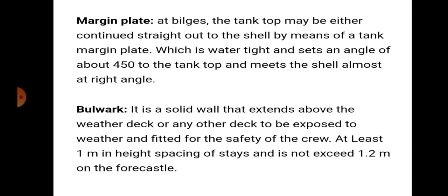Then margin plate. At bilges, the tank top may be either continued straight out to the shell by means of a tank margin plate, which is watertight and set at an angle of about 45 degrees to the tank top and meets the shell almost at a right angle.